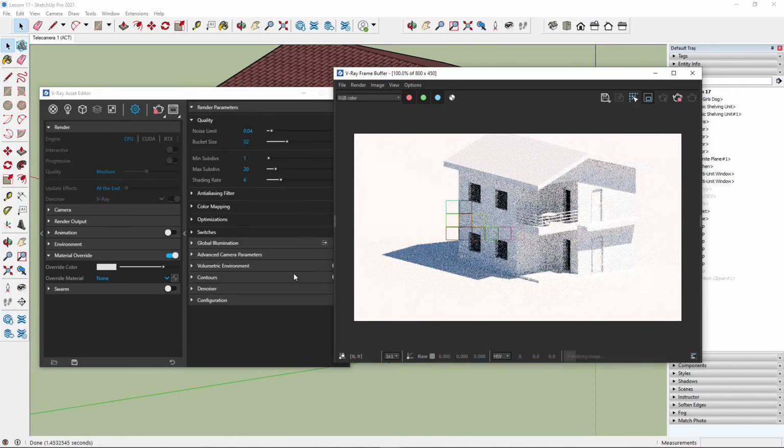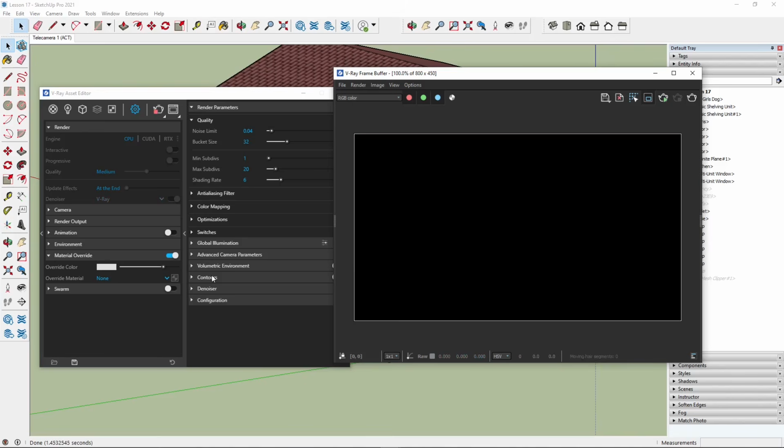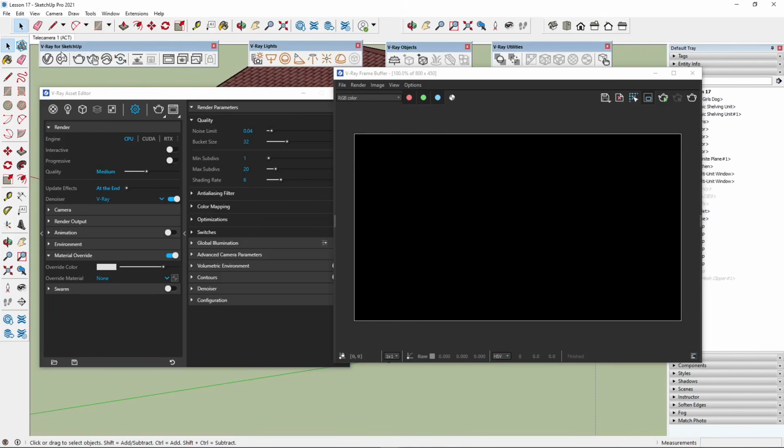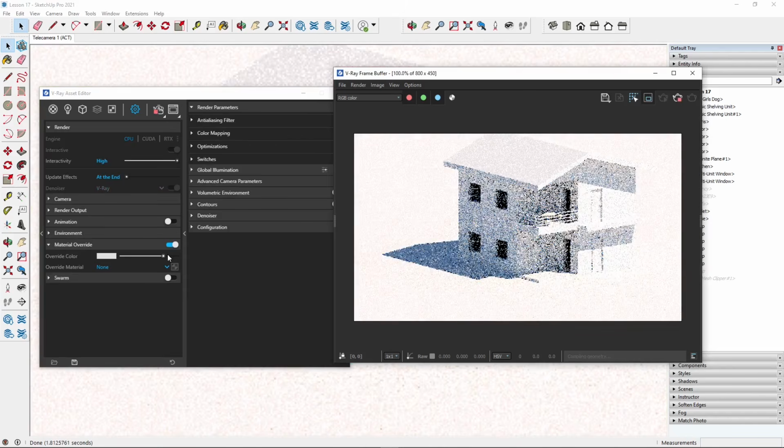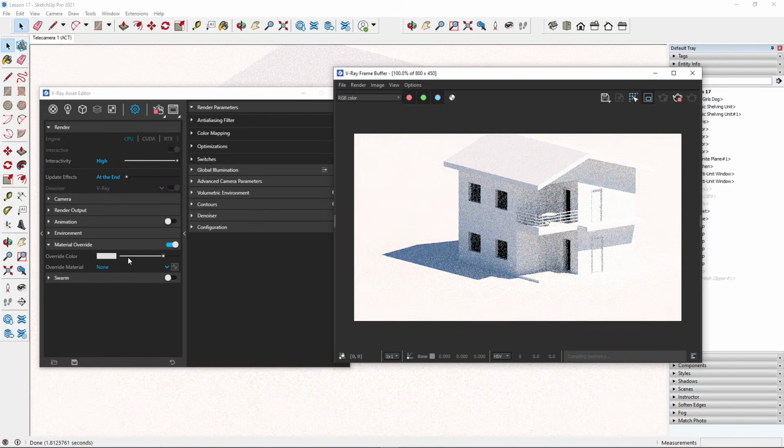Now another tip is never assign a color which is gonna be too white. Always stick with a very bright gray, but never go too far with the white, because we don't have total white ever. Also, if you have really pure snow, it's never gonna be total white, so it's gonna be a little bit, let's say, dirty with the gray.